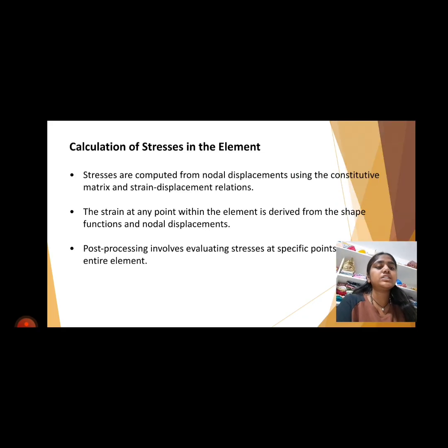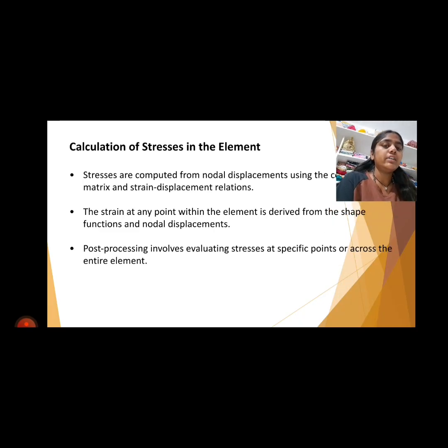Then calculation of stresses in the elements. Stresses are computed from nodal displacements using the constitutive matrix and strain displacement relations. The strain at any point within the element is derived from the shape function and nodal displacement. Post-processing involves evaluating stresses at specific points or across the entire element.